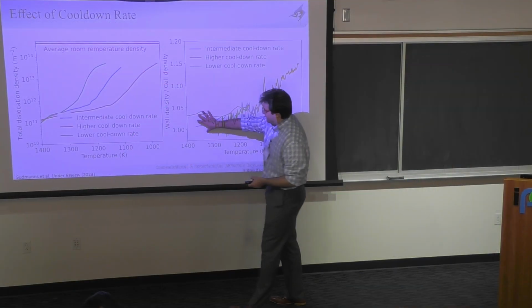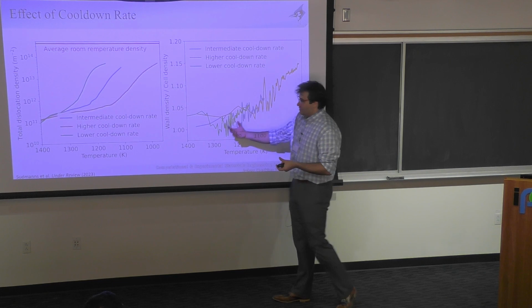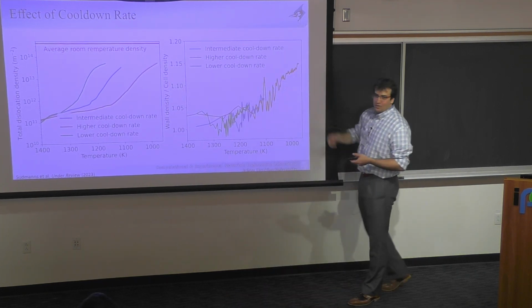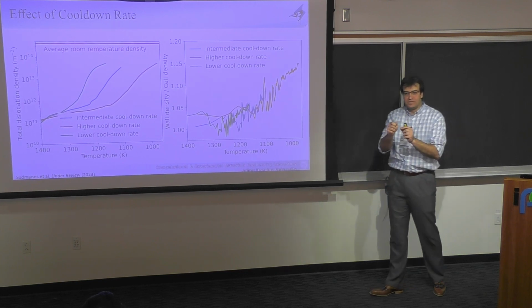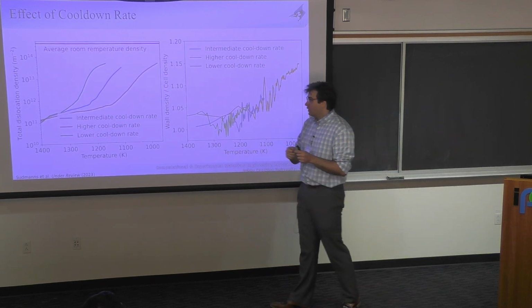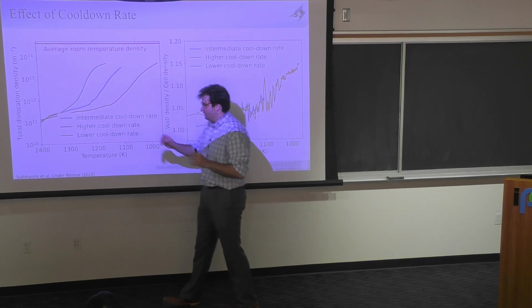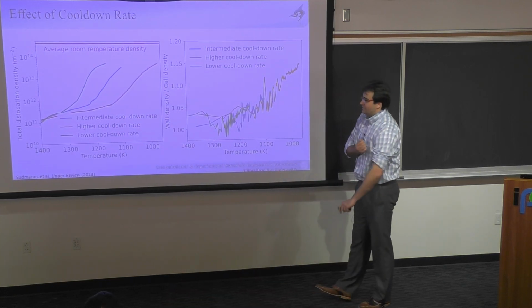But nevertheless, if you look at the actual density of the dislocations in the walls versus the interior, the cooling rate doesn't really have an influence. So if you're only interested in understanding the mechanism of how these walls form, maybe this doesn't really matter. Maybe the cooling rate doesn't really matter.